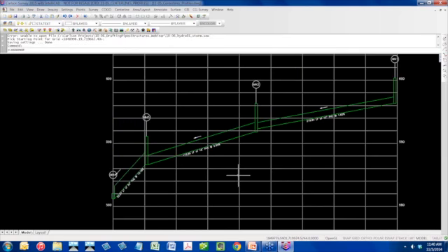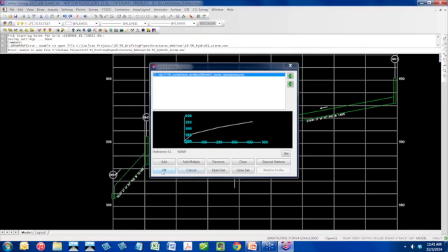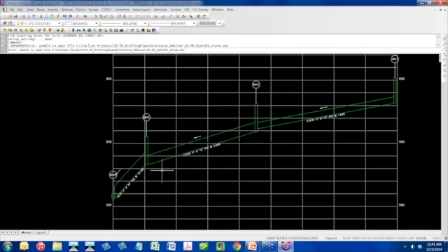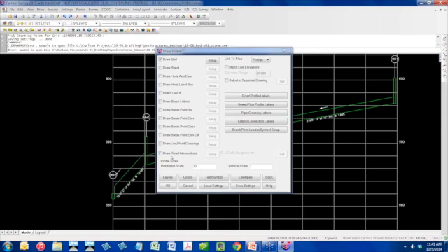The last thing I'm going to mention here, let me just go right back into Draw Profile real quickly. I'm not going to redraw. One more question, Jennifer. Sometimes Carlson won't accept a 2D polyline for a profile. Are there any polyline properties that need to be set a certain way to work? A 2D polyline for a profile. I'm not sure what that means.